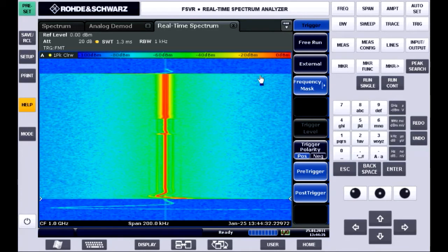The mask became active immediately. I had a trigger event down here where the power turned on, so I see before that and I see 500 milliseconds after that is written into my memory. And this is why I set up 1.3 milliseconds, because it fits on the screen nicely. There's nothing magic about that number.